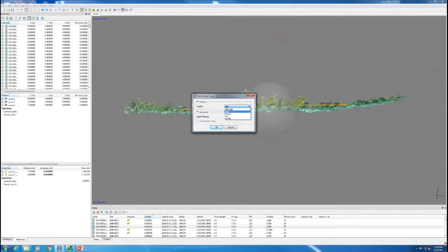And then once you've got your bounding box set and you're happy with all the points in your sparse cloud, you would go to workflow and build dense cloud. And here again you've got a couple different build parameter options. We can go and change the quality. I usually leave it at high. I think if you did ultra high, you'd be waiting a very long time for this to finish unless you were working with a small object and a small number of photos.